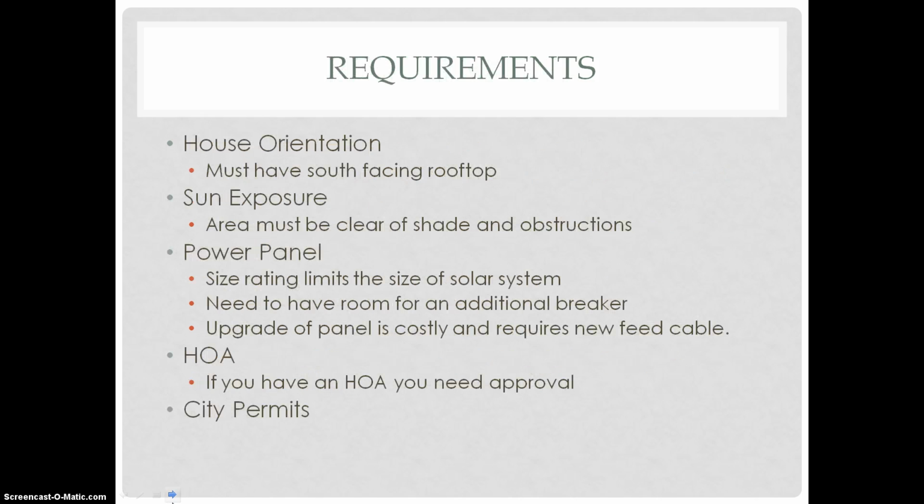There are requirements before installing a system that you must observe. Your house must have a south-facing sloped rooftop. Your sun exposure must be clear of shade and obstructions. There are power panel requirements where the size and rating limits the size of the system that you can install, and you need to have room for an additional breaker.